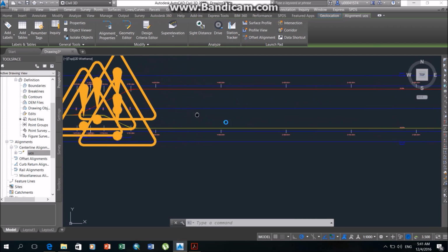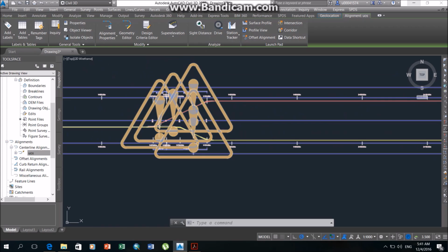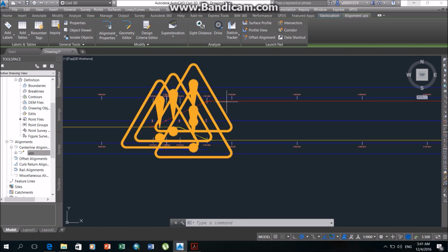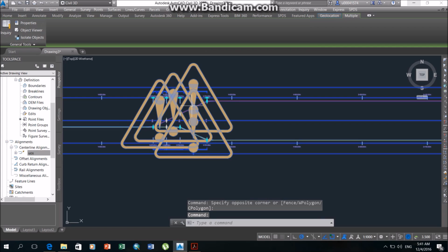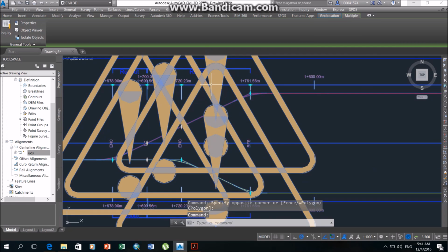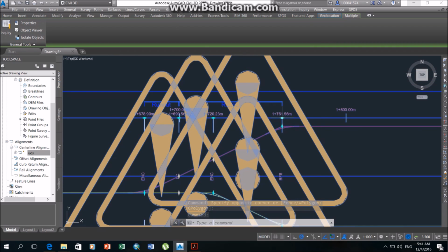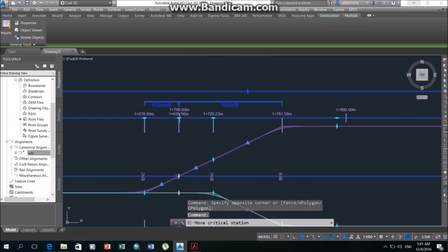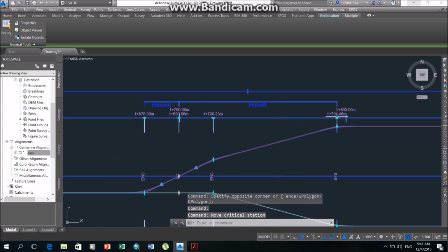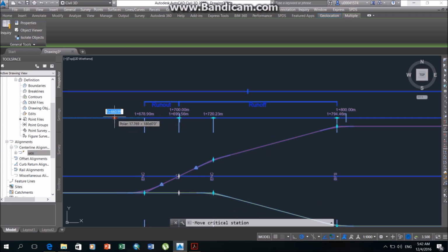Here's our superelevation. Now you see a lot of wrong signs. That means that the distance covered by the 6% slope isn't enough. So what you have to do is increase the runoff and runout distances. How can you do that? Just select over here, you will see some lines. Just extend them. And you will see the signs are going out. One over here.